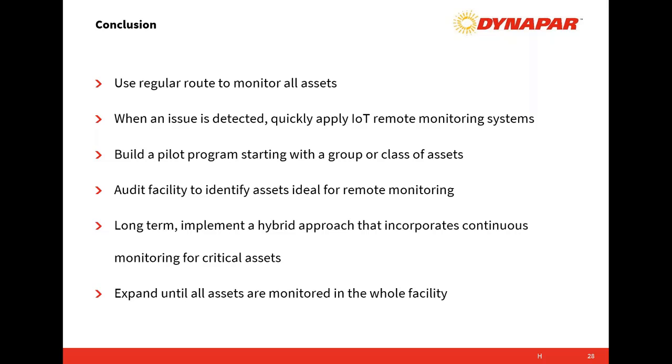That's why having both of those data streams is really key. You may see it in the vibration data, and then you confirm where you're at in terms of the PF curve by checking for indications in temperature. When we see both a change in vibration and a significant change in temperature, that tells you you're much farther along in the PF curve, and some maintenance action to verify this physically might need to be done.